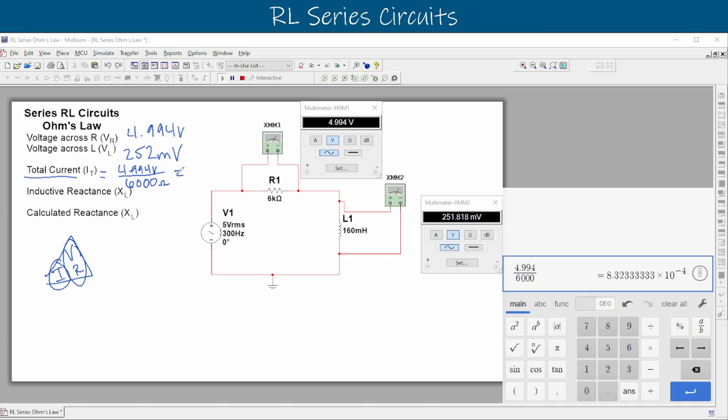We'll see that we can move that back by 2 because it's at that -4 location, and that's not engineering notation, so we can move it back from this decimal point here back between the 2 and the 3, right here. So that's going to give us an 832. So let's plug that in. Now we have a total current of 832 microamps.